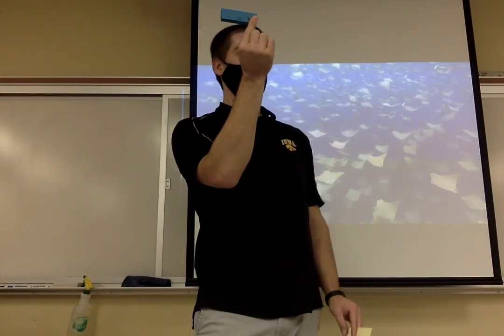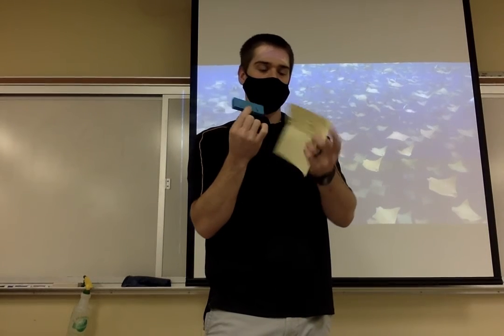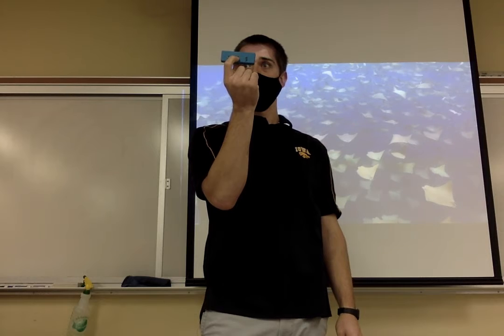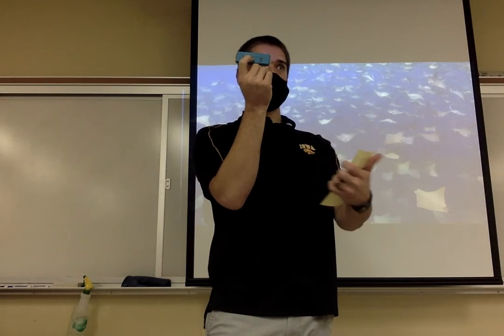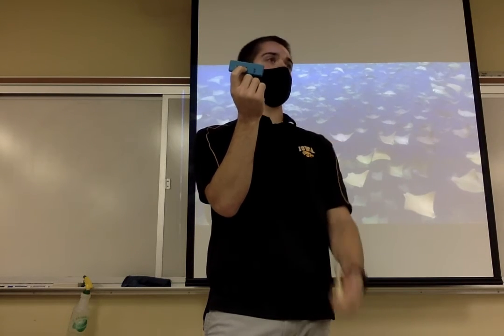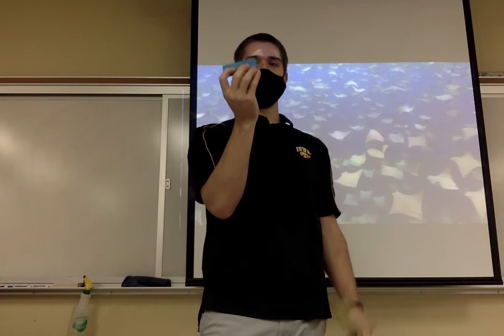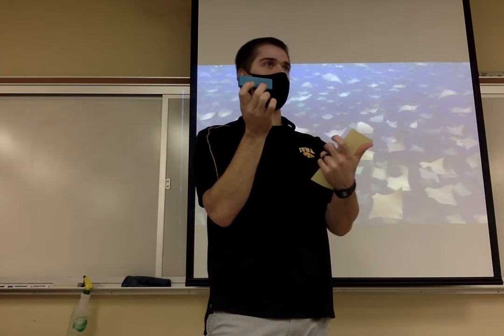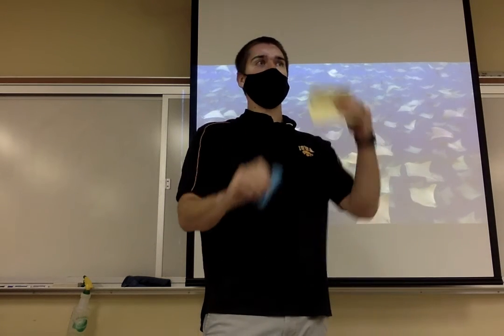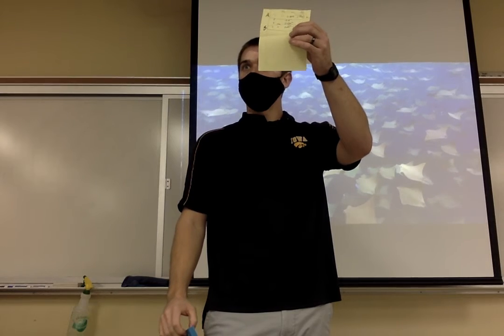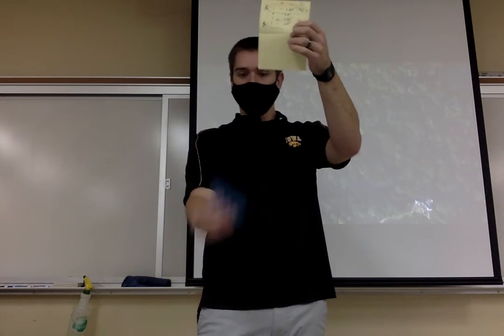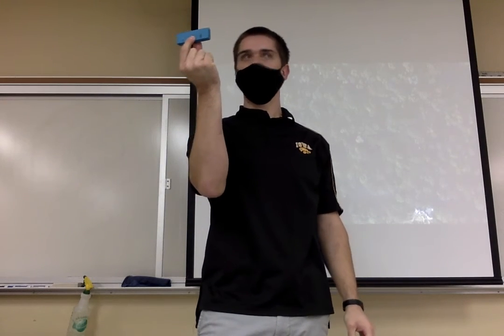So on block A, in the middle, I did a 3/16 inch hole. On the left side, I went down a drill bit to 11/16. On the right side, hole 3, I went up to 13/64. The design specification should be my drill bit size. If I use a 3/16 drill bit, my hole should measure 3/16 of an inch.